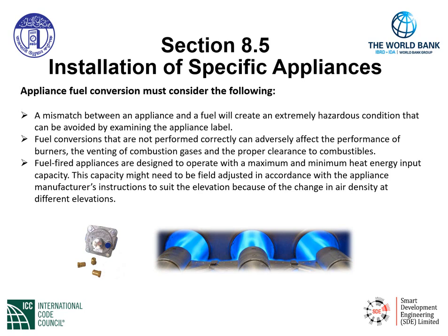The appliance fuel conversion must consider the following items. A mismatch between an appliance and a fuel will create an extremely hazardous condition that can be avoided by examining the appliance label. The appliance label indicates the source of fuel that needs to be supplied to that appliance for proper operation. Fuel conversions that are not performed correctly can adversely affect the performance of burners, the venting of combustion gases, and proper clearance to combustibles.